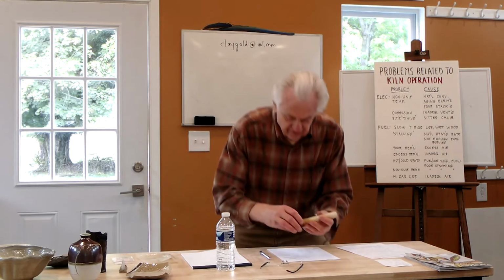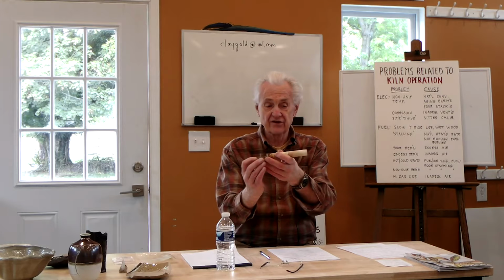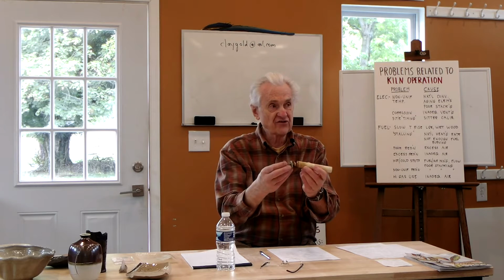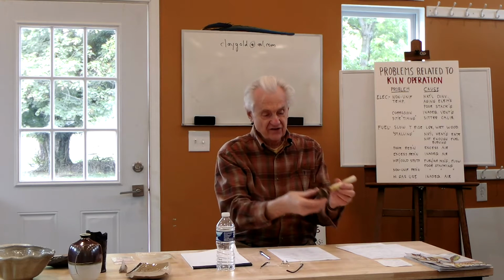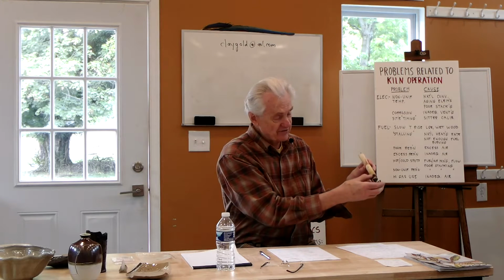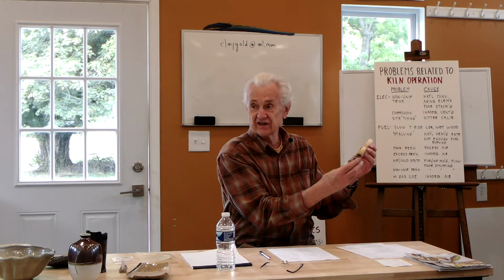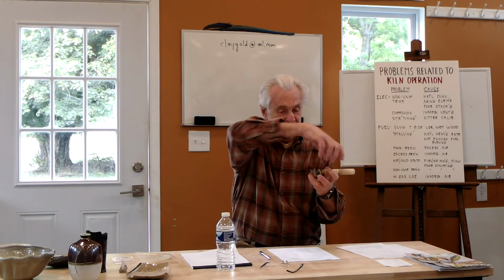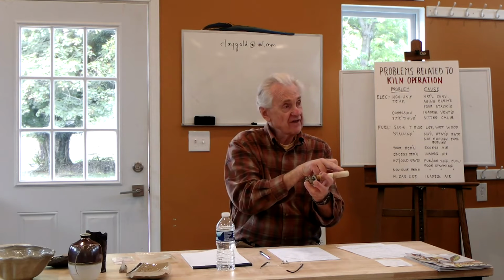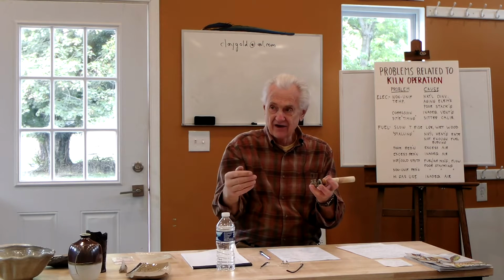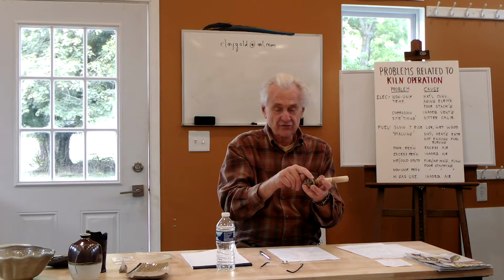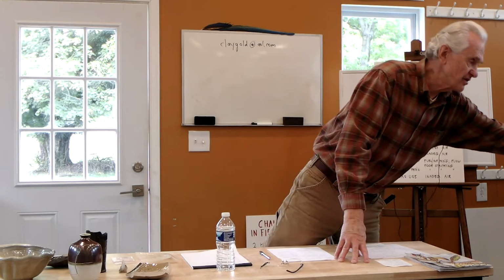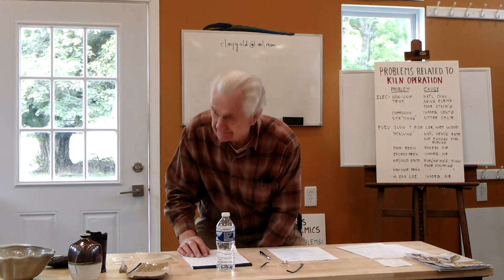And here's another example. This is the tube. You may recognize it from a kiln sitter. This is the outside where it mounts on the kiln, and this is the part that sticks in. The ceramic tube was actually attacked by the acid in the kiln, and you can see the fixture that held it into the kiln was completely rusted away. The reason this is in this location is because this is on the outside of the wall of the kiln. This is where the acid fumes from the inside of the kiln met the air on the outside, and the air has moisture in it. So right there, where the gas and the air met, it formed sulfuric acid, and it just ate away the ceramic and completely ate the supporting metal that holds it.